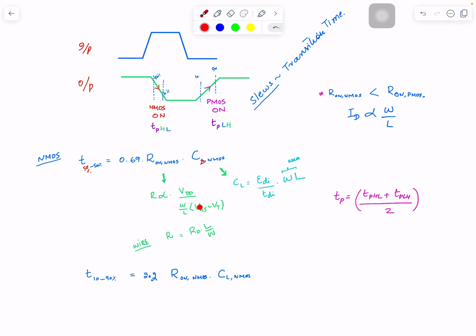So with this equation, as I said, the benefit of equations is you can find some relationships. If I want to reduce resistance, what can I do? I can reduce supply voltage, but keep in mind that reducing supply voltage has another effect: the VGS minus VT term gets smaller, so the resistance will get higher. So there are two impacts of supply voltage.